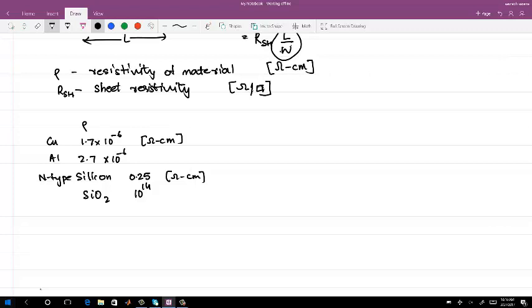So what all materials do you have when you are trying to realize the resistance on silicon? You have metals which you use for connections. You have N-type, P-type silicon, polycrystalline or diffused or whatever they are. Then there is another thing called metal silicides, where you have the silicon metal implantation in silicon. Then you have silicon dioxide which you use for isolation and others.